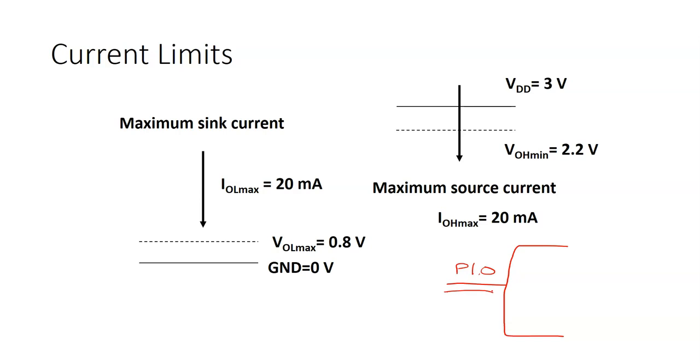When we talk about the current that can sink, this is when the circuit is in a state where current is flowing into the pin and into the GPIO, and sourcing is when current is flowing out of the pin into that external circuit from the microcontroller. In both of these cases, for the majority of the GPIO pins, when they're not set into a high drive configuration, the limit is actually, this slide is wrong, should be 6 milliamps.